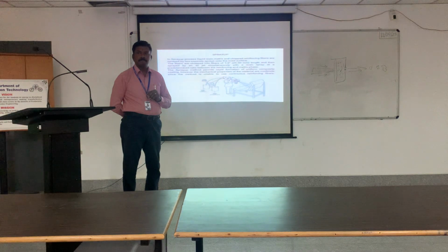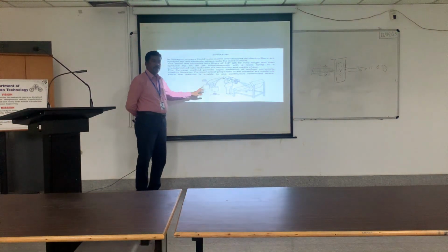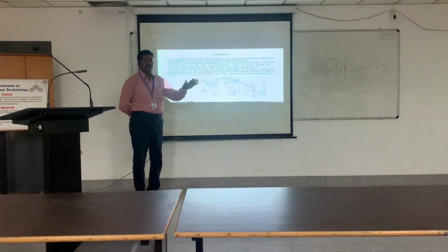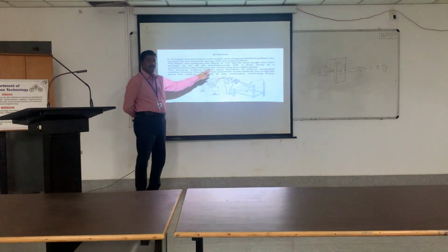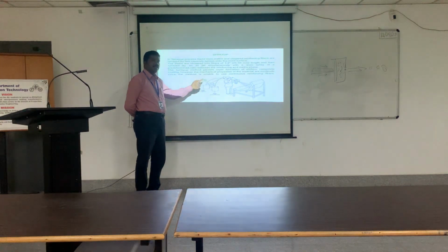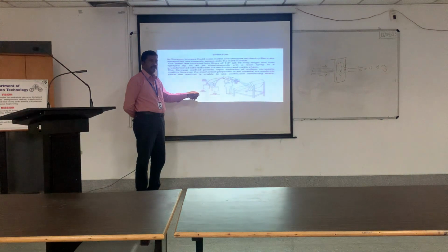Catalyst actually actuates the reactions. Very good. Accelerator speeds up the process. Very good. The resin will be in the form of liquid. We want to convert the liquid into solid. That is the process of curing. After the composite is made, it has to get cured. So to initiate the process of converting from liquid to solid, the catalyst will be used. If we add some amount of catalyst, that moment itself it will start the reaction for converting this liquid into solid.